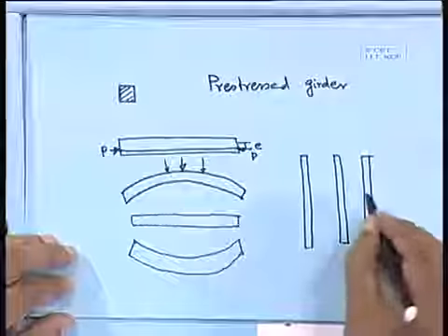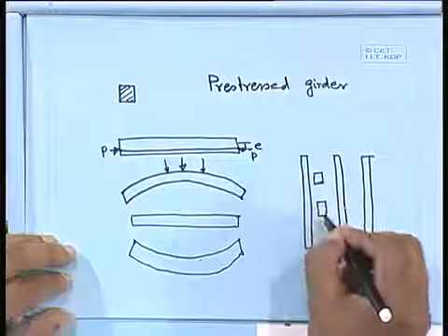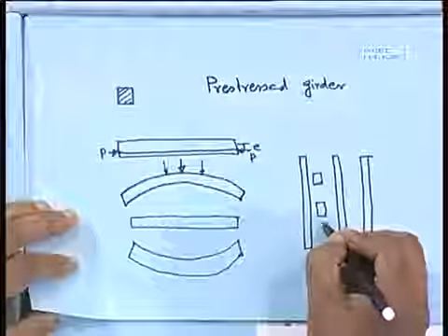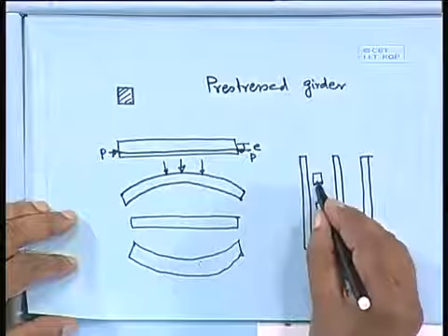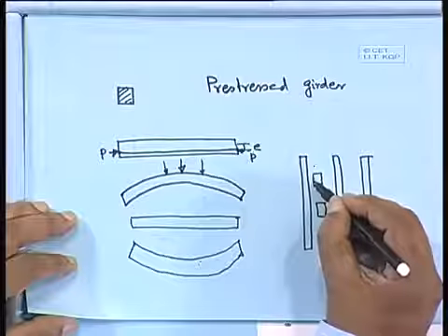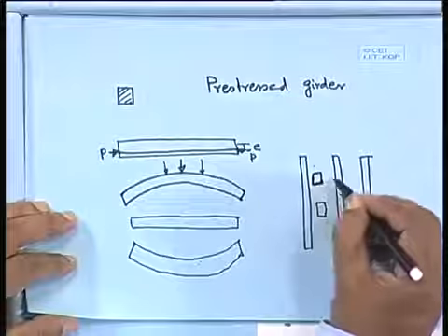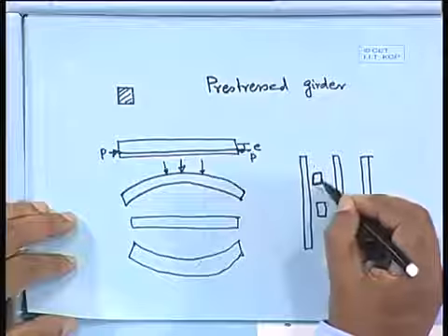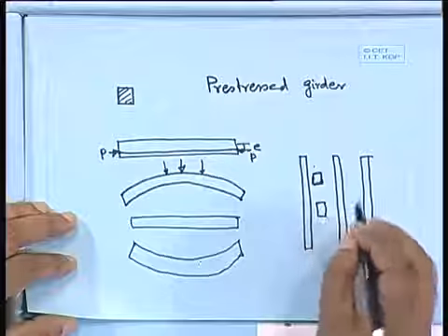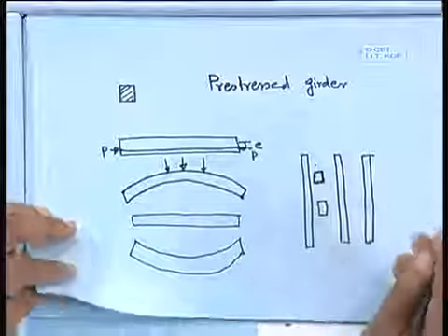Now here we are having that wheel load. This wheel load is coming as a concentrated load. So if we have the concentrated load here, how shall we take the effective width of the loading? The impression directly, we do not take it, we take a little more. So how much more we can take, that we have to find out. In this case, there is always one wearing coat.